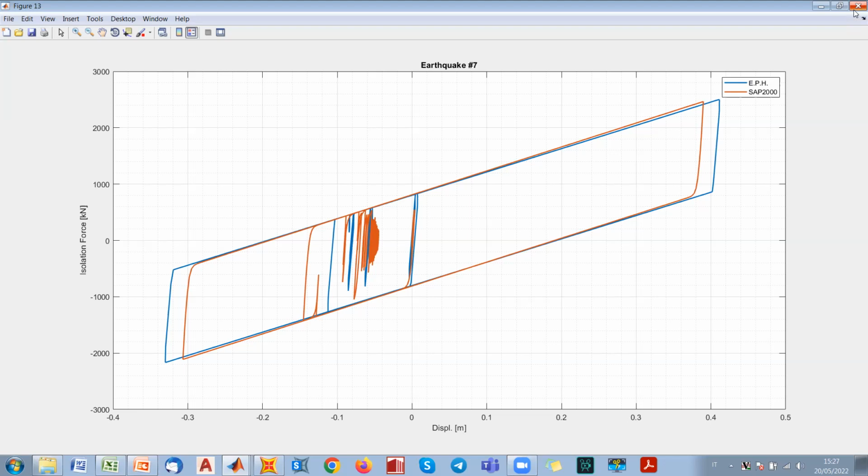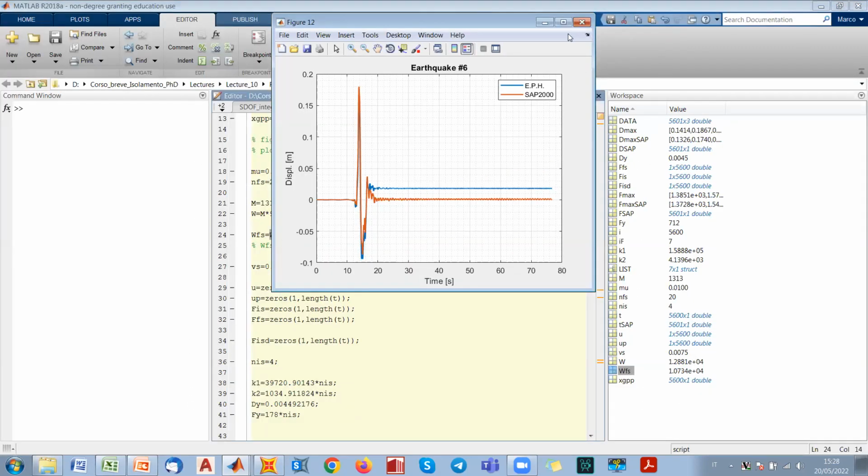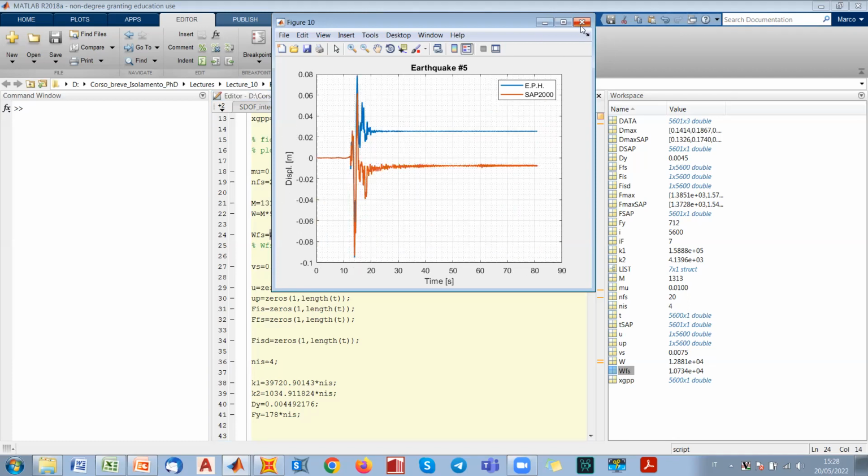if we are able to perform just a gravity load application. But if you want to consider the lateral response of the isolated structure and you don't want to build the finite element model, you can just compute the average total value of gravity loads applied to flat sliders, and you come up with a fairly good estimation of displacements. Also for residual displacements here, you see SAP 2000 goes back to 0 because of the influence of the superstructure. So here we are pretty close to 0, but values are very limited.